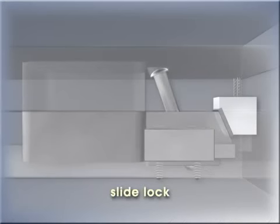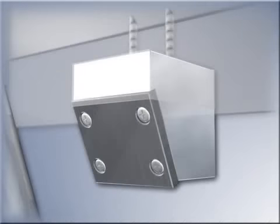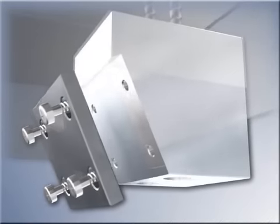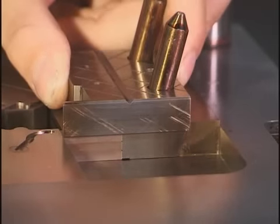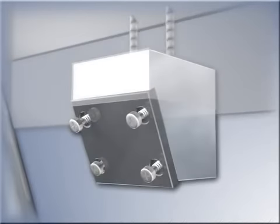A heel block applies pressure to the slide block when the mold is clamped. Due to the forces applied to the heel block, a small wear plate can be used to ease replacement when wear is evident. The angle ground onto the back of the slide block corresponds with the angle on the face of the heel block. This angle is typically 10 to 20 degrees and locks after the slide has been put in place by the actuator.